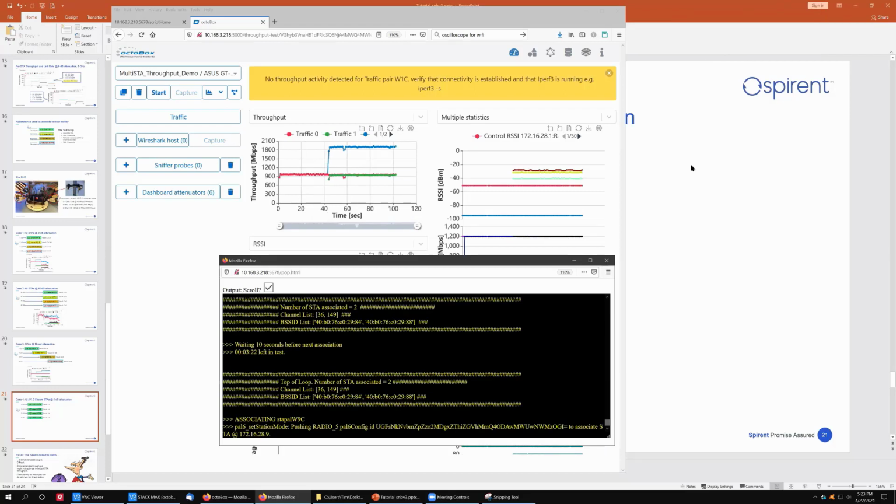And another question came in, which I think is the same. I'm going to read it anyway and see if you hear it differently. Carlos asked, what if the most capable stations had the 30 and 45 dB attenuations instead of the slowest ones? Isn't radio assignment purely done based on station RSSI? I think that's the same question that Craig just asked. I mean, it sure looks like it.